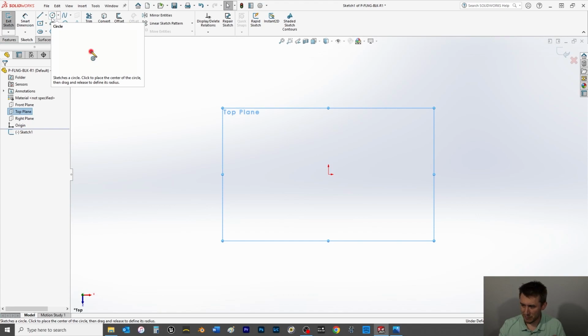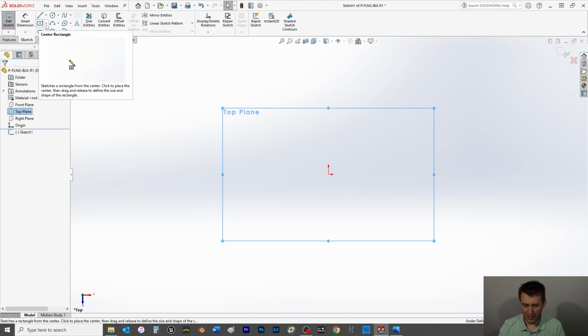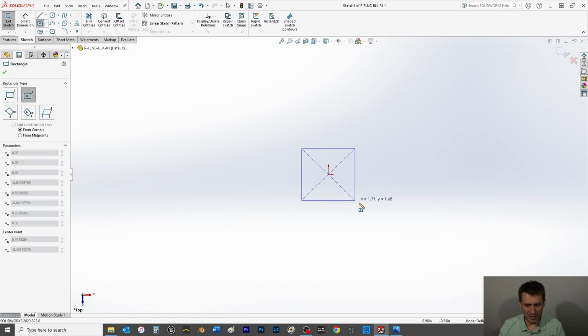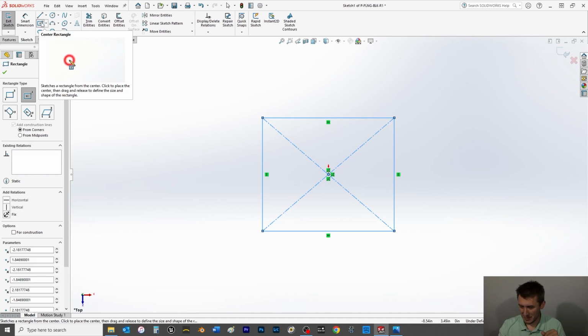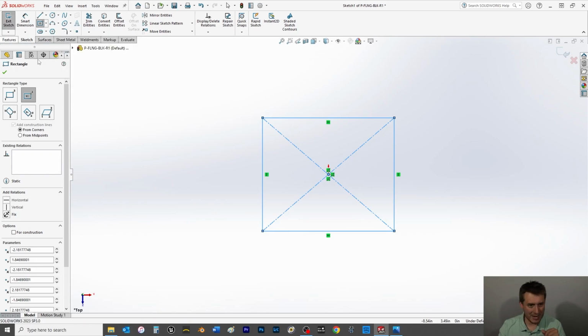Let us first create, how do we want to do this here? We'll go with a rectangle. We're in the sketch tab to do a rectangle. I'm doing just a center rectangle. I always like to make the majority of the geometry have some center coincident to the origin. And let's see here, let's slap some things together. A radius of 40, which means that's 80.